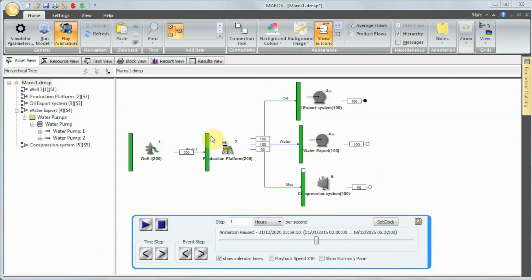Year 5, boom. We had full capacity, right? So everything's producing at full capacity, 200,000 barrels for each one of the well and separation, and water is at full capacity now. So when a failure occurs now, we have to reduce everything to 50%. Why is that? Because if you cannot produce 50% of the entire water production, you need to shut down the separation by 50%, and this is going to impact the oil by 50%, right? So this is why production profiles are so important, right?